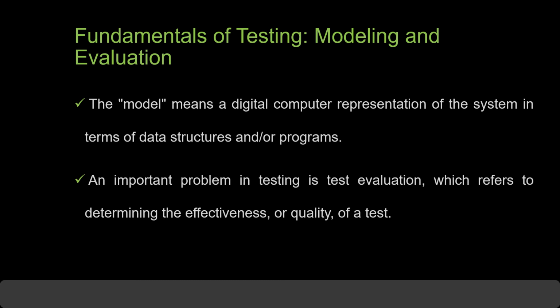It is usually done in the context of a fault model, and the quality of a test is measured by the ratio between the number of faults it detects and the total number of faults in the assumed fault universe. This ratio is usually referred to as fault coverage. Test evaluation is carried out via a simulated testing experiment called fault simulation. We'll be studying fault coverage and fault simulation in the coming modules.